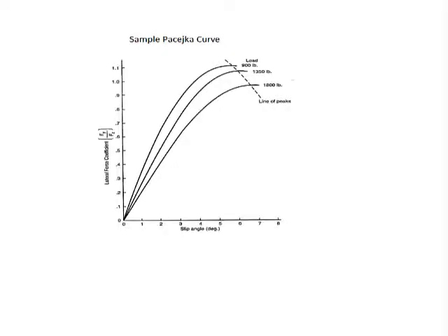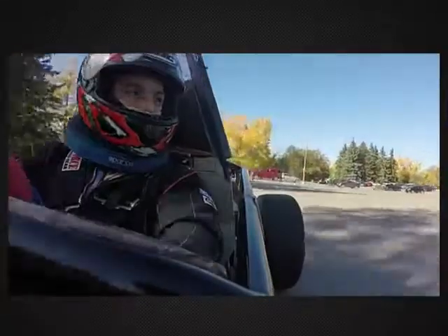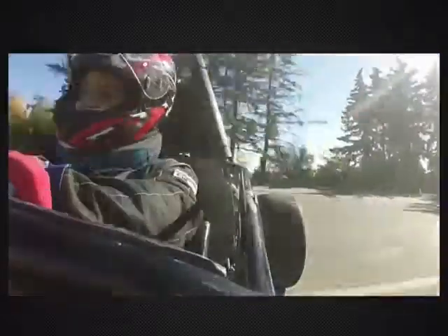When the car accelerates, this causes the weight to transfer from the front wheels to the rear wheels. This simple process relies not only on geometry, but also on the tire compound, which can be correlated to the Pacejka tire model. Using experimentally derived constants, we can convert vertical loads to longitudinal and lateral forces at the maximum slip condition. For any given test track, the vehicle is not only accelerating, but it's also braking for a significant